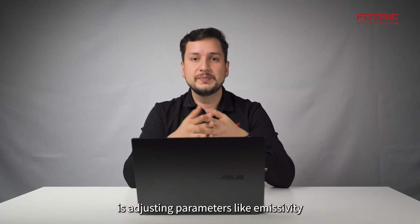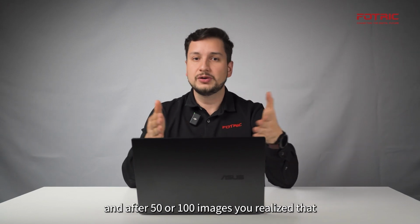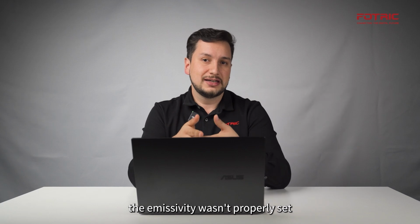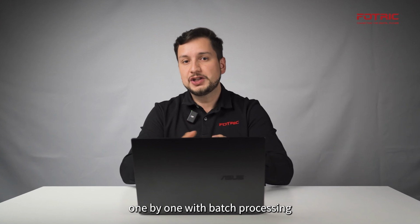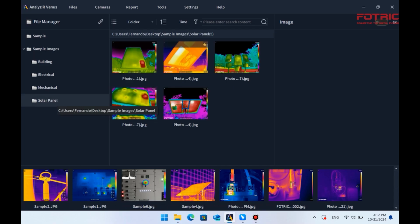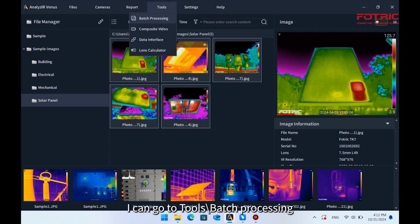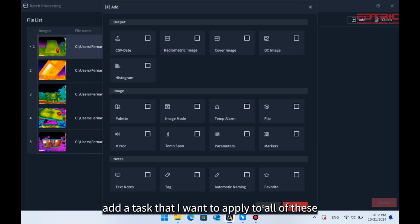Another common job that might take a lot of work if you do it manually and one by one is adjusting parameters like emissivity. Let's say that you completed an entire inspection, and after 50 or 100 images you realized that the emissivity wasn't properly set. So you have to go back to the images and adjust one by one. With batch processing, I can go to, let's say, my solar panel images, select all of them, and because I have a different material on those solar panels, instead of the typical 0.95 emissivity, I can go to Tools, Batch Processing, add a task that I want to apply to all of these,